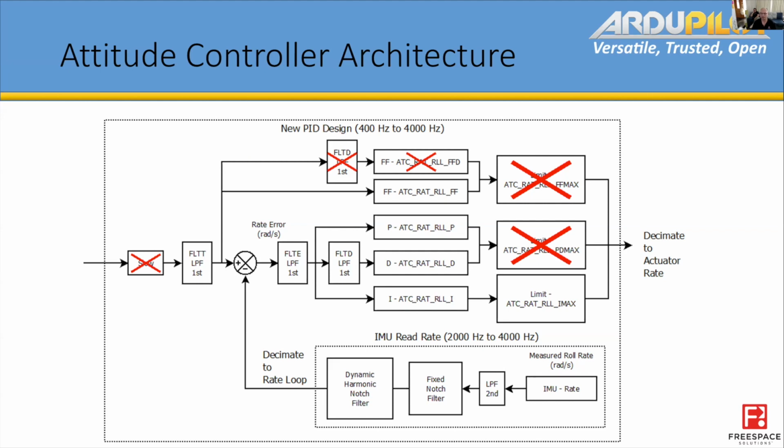And in order to get an aircraft flying effectively, this filter has been really useful even on roll and pitch. And for really high-end yaw control, I've only ever had to do that on one aircraft. It was a racing aircraft, but these two filters come back into play with D-term, especially if you're dealing with aerodynamic bodies on racing aircraft, and they really can do with the extra precise yaw control.